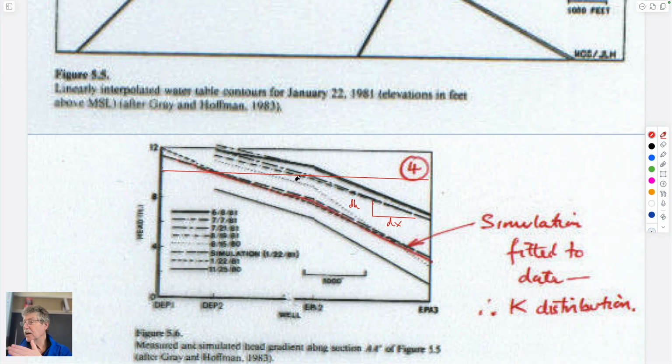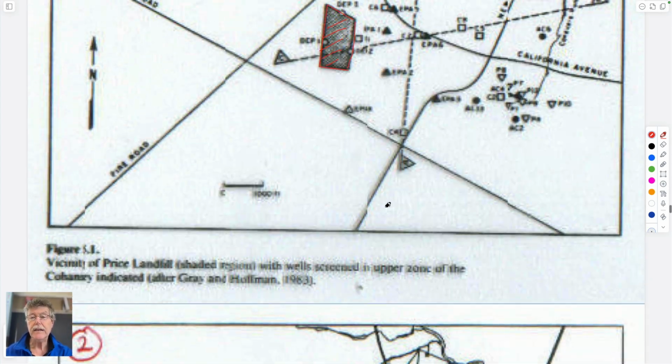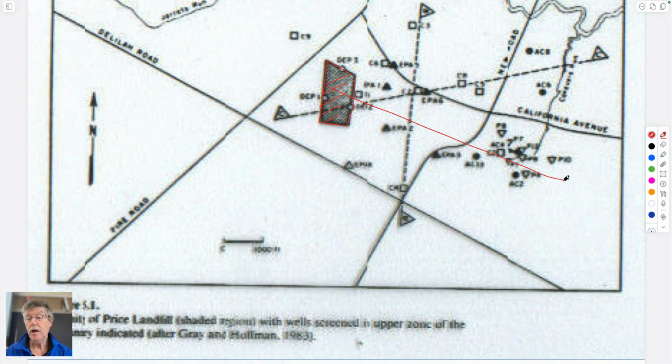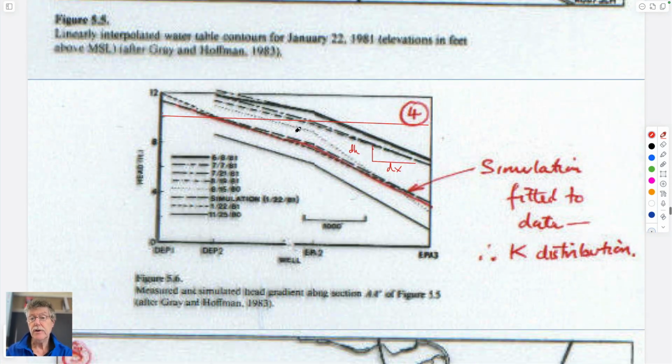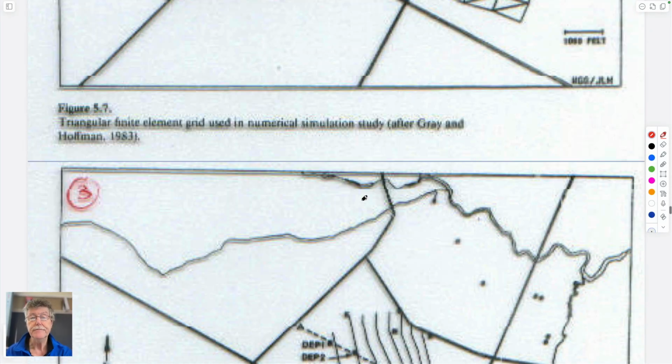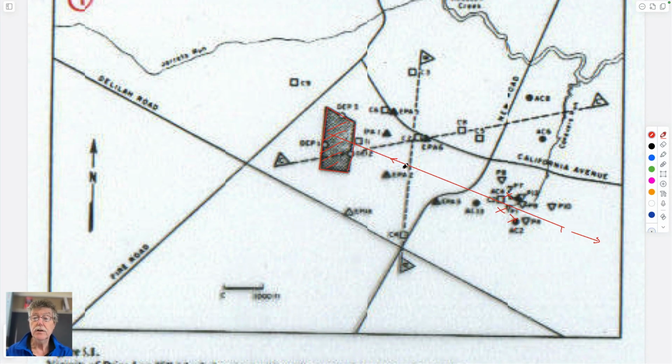And so you might want to do a section 90 degrees to that, because then you might have a groundwater flow. So you get the orientation of the maximum gradient. And if you can project that maximum gradient onto a plot where you've sampled and you know there's a problem, then you can look downstream or upstream. And if you have a plot like this, you definitely know which direction is upstream and which direction is downstream. And so in this case, you know this is upstream, you look up here, you drill some more wells, and